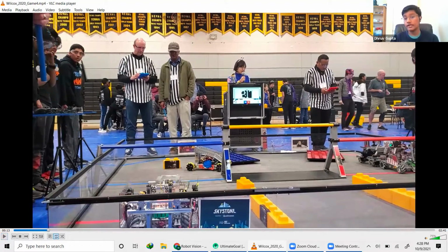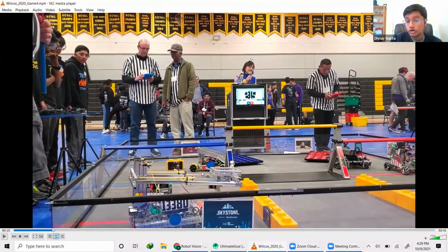And now this is one of the places where you can really notice how helpful vision technologies such as Vuforia and TensorFlow are. If we'd been using an arbitrary distance, like let's say we detect the target and then we always just move 12 inches forward, try and grab it, and then move 10 inches back, turn 90 degrees and go forward, we would not have been successful because our interaction with this robot pushed us maybe like 5 to 10 degrees to the left, and then we went back around 8 feet. So that distance really exacerbated that turn. So now we're in a very unideal position as to what we would have programmed it to. We would have expected it to be maybe 4 or 5 more inches to the right, and we would have expected our robot to be perfectly straight. But as you can see after this turn, the robot is curved to the left.